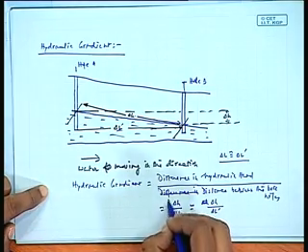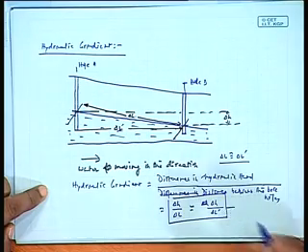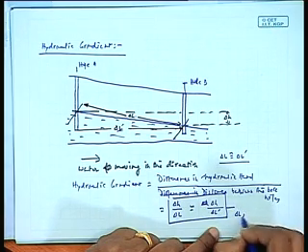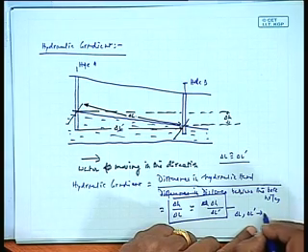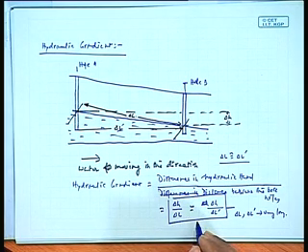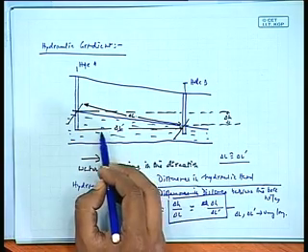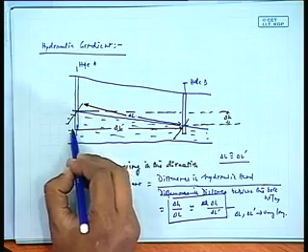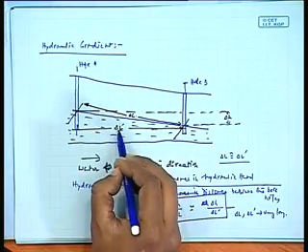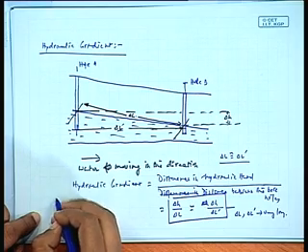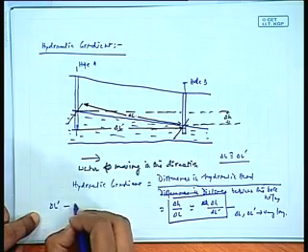In most cases, when the aquifer is a very long aquifer, when del L and del L dashed are very long, then we can consider this to be almost the same, isn't it? But for almost all practical purposes, if otherwise not specified, this would mean this distance. Remember this. If it is not otherwise mentioned, this is exactly the distance that should be covered as del L dashed. So in all practical purposes, to make the correct judgment about the hydraulic gradient, del L dashed should be considered.